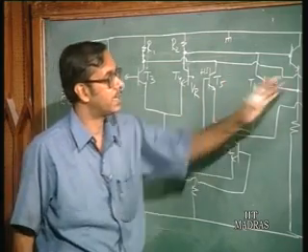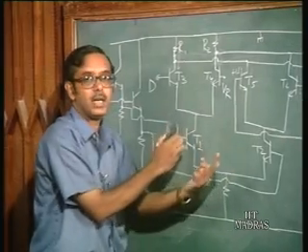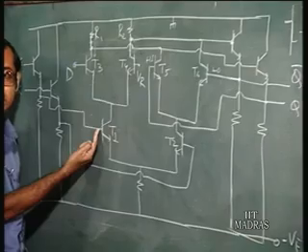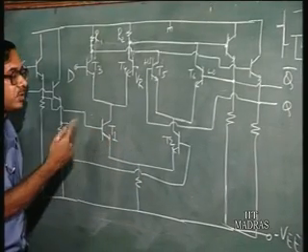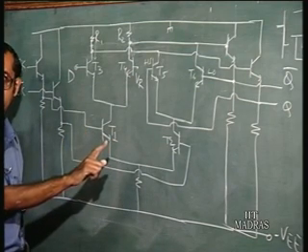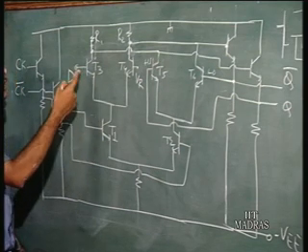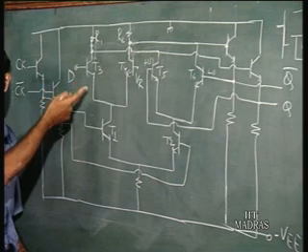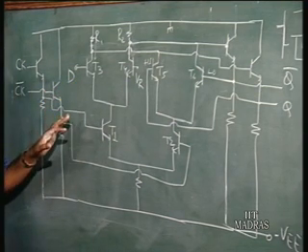What changes do you make in that second D flip flop? You have to just change the clock inputs. Just like you have fed the clock input at T1 and the clock bar to T2, you have to just change that. You have to feed the clock bar to T1 and the clock to T2. That will take care of that, and the D input of the second flip flop is going to come from the Q output of the first flip flop. So, if you have that, you have a master slave D flip flop.